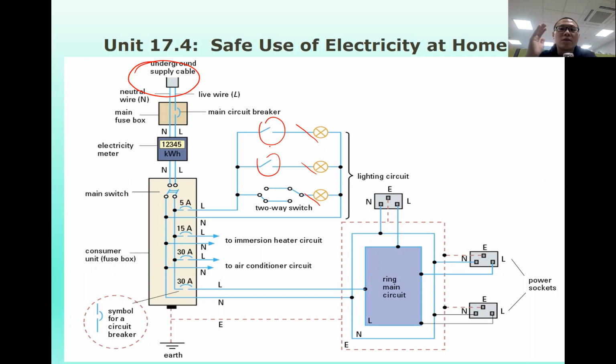Okay, in the event that these two lines of defense fail, I have all the switches connected together, and they are connected to a circuit breaker, which is the third line of defense. Your first two lines of defense will disconnect the individual appliances. The third line will disconnect the entire circuit for the room, maybe 3 or 4 appliances. So this is where the circuit breaker comes in. You'll find that different rooms will have different circuit breakers here to control. And even better, all these rooms or the entire house will again be connected to a bigger circuit breaker. So the fourth line of defense is another circuit breaker.